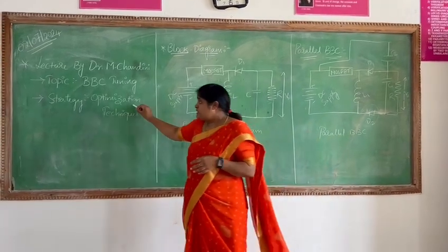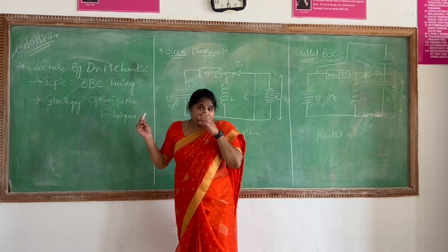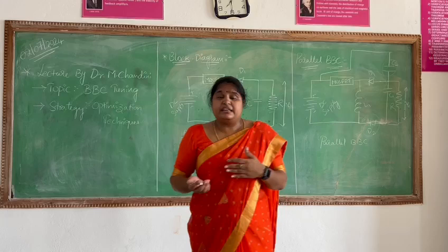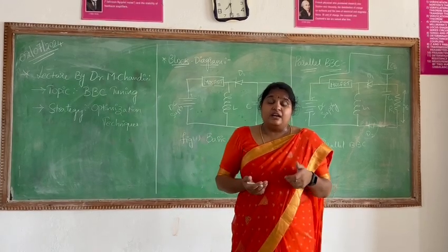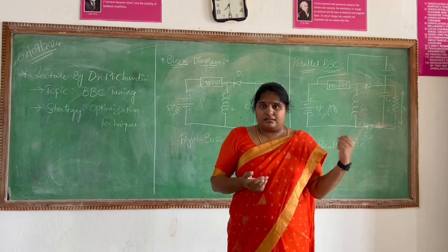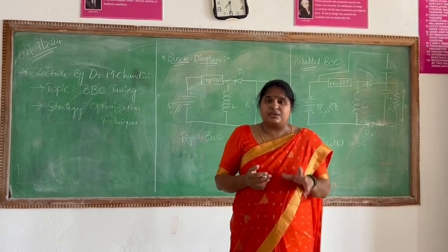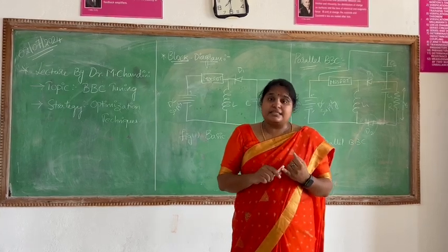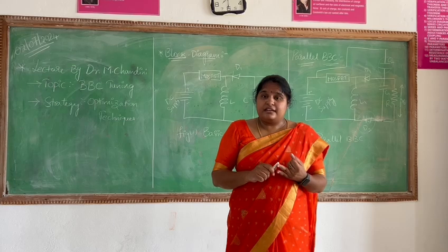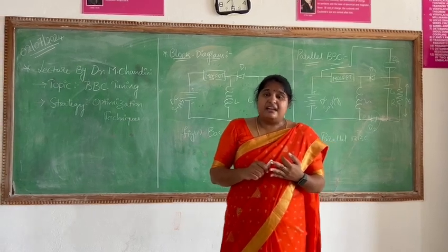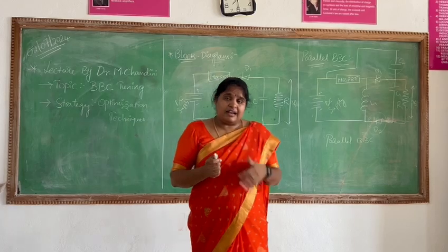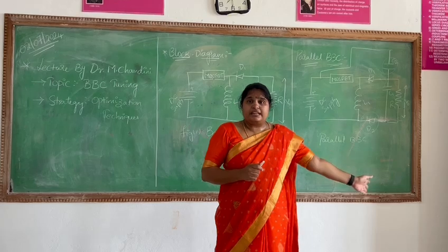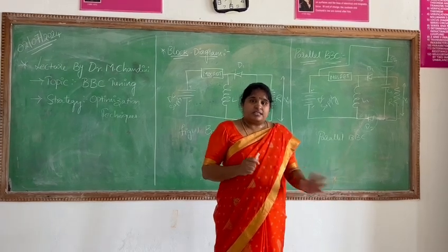Next, the optimization. Here we have already mentioned the optimization techniques. What optimization techniques are we using? Some of the AI/ML and deep learning techniques are incorporated for optimization of the buck boost converter parameter tunings. What parameters are we tuning here? Mainly the duty cycle of the MOSFET, second the inductor and capacitor values, and last but not least, we are tuning the efficiency and the power quality of the ultimate output.